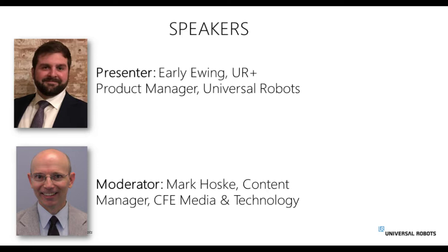And those benefits for a cobot, even in an industrial application, still contribute to the ROI on that application. So my typical advice there is if it's within the performance envelope of the collaborative robot, the cobot is typically the better choice because of that ease of use and that ease of programming, even if it's not going to be a collaborative application. Now, of course, for collaborative applications, your cobot is typically your only choice if you want to fulfill that. And within our model range, it typically depends on your payload and reach requirements.